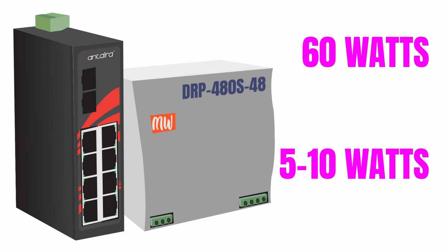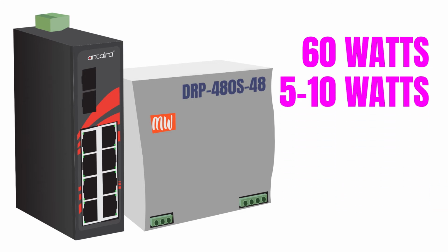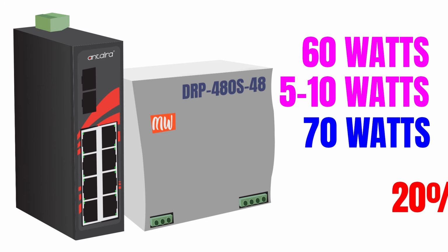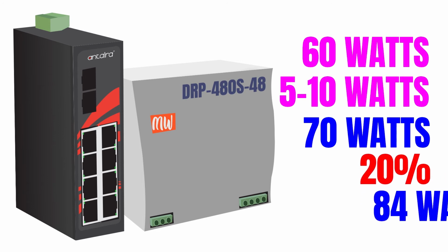Add in the 5 to 10 watts for the switch, and that puts you at around 70 watts. If you add in the extra 20%, you still have less than 85 watts.